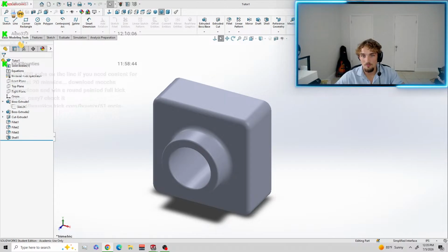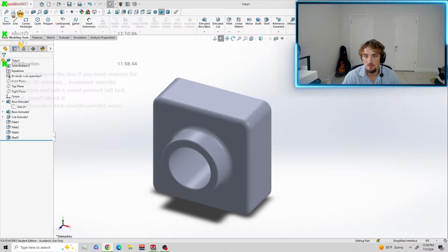Your graphics card is not officially certified by SolidWorks, or a crucial display setting like large assembly mode is turned on. Officially restricts real view graphics to certified workstation class GPUs like NVIDIA Quadro. If you're using a consumer gaming graphics card like NVIDIA GeForce or AMD Radeon, the option will be permanently grayed out unless you apply a workaround. Yeah, I have an NVIDIA GeForce, so that's the problem.